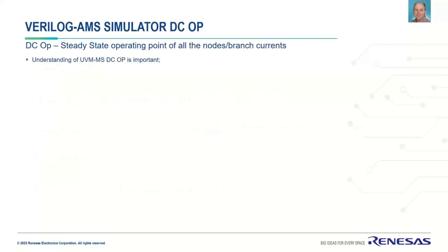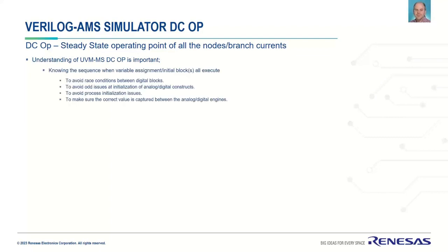Right, the AMS simulator. It's really important when you're doing mixed mode simulations that you understand how the analog and the digital interact, how initialization works, because UVM does a lot of stuff during the build phase at time zero. You've got an analog solver doing this. If you know the sequencing, you can get it perfect. If you don't, you might go, it was working, now it's not.